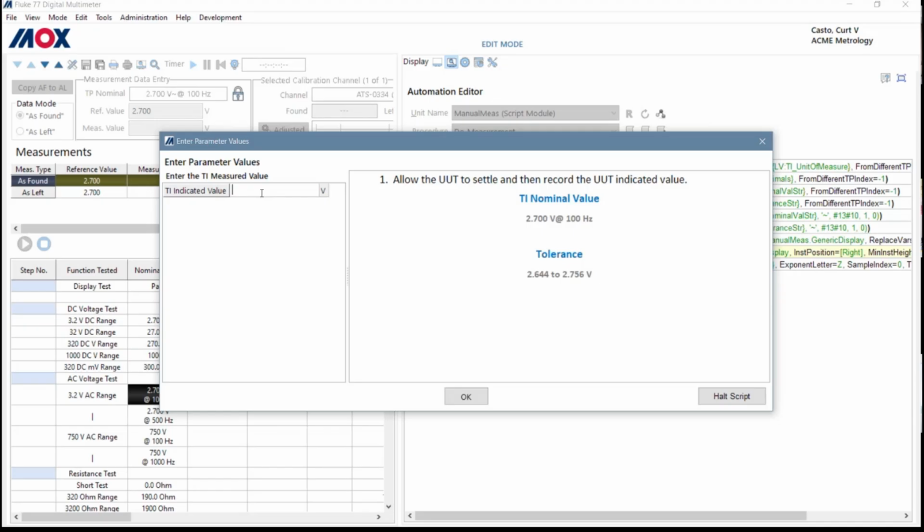Right. And with our pin gauge data sheet that it creates, it will do a prompt similar to this. But if you're doing it manually, then it will give you basically the one end, first end, middle, second end, right, to enter those values. And then, you know, compute the average from that.